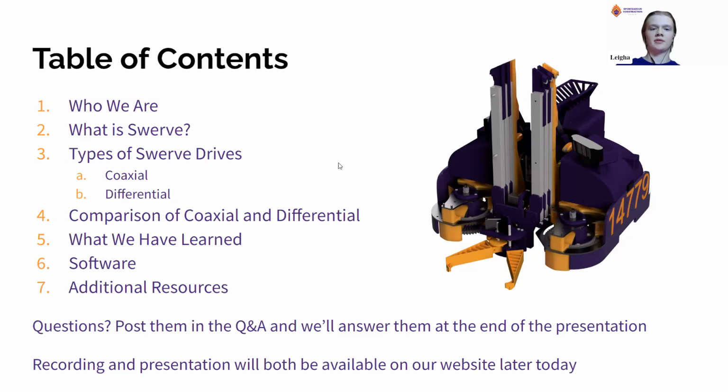There was another question about the plastic-to-plastic interfaces on a robot, and whether those cause any issues with friction or wear. For a majority of our plastic interfaces, those are going to be PETG to nylon or nylon to nylon. Since nylon is a very low friction material, there isn't that much wear there. We also apply silicone grease to the parts where there would be excessive wear to make it even lower friction. So it hasn't really been an issue.